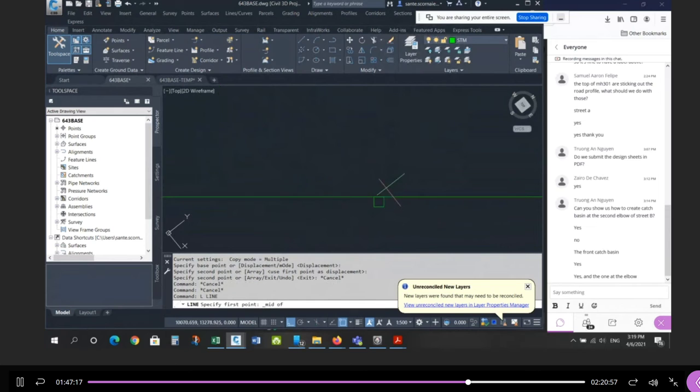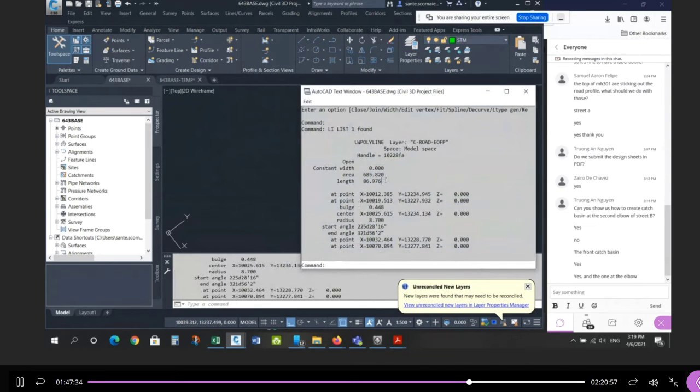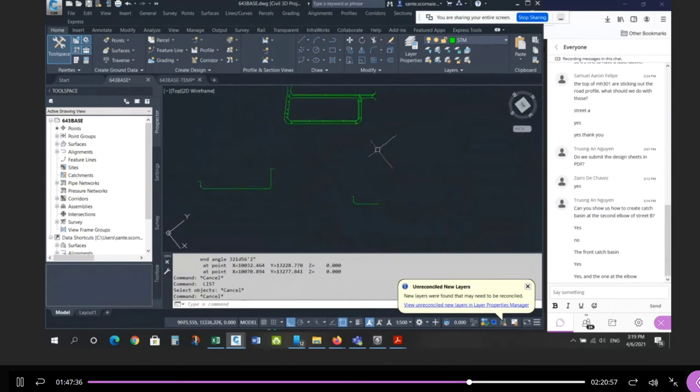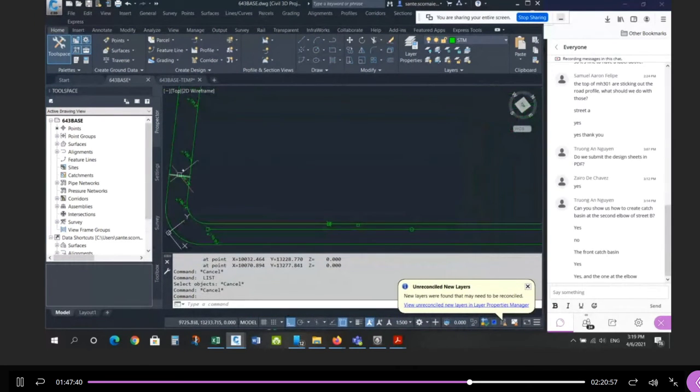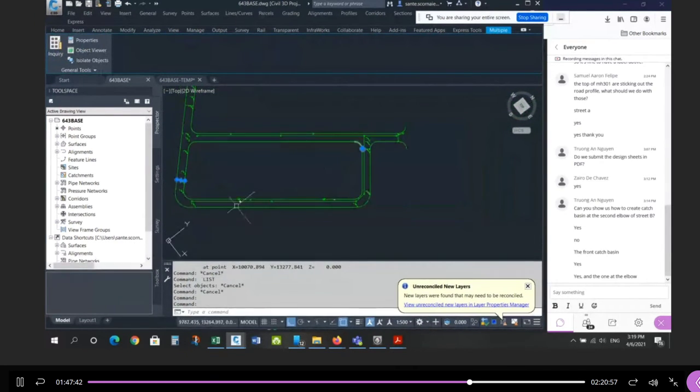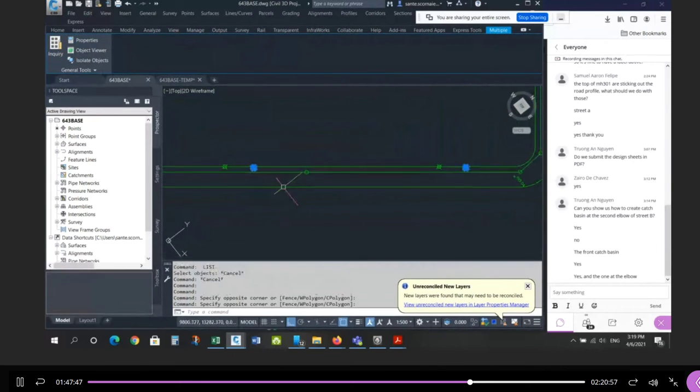All right, I'm going to draw a line from this midpoint, trim it off here. I don't even need the catch basin anymore. And then here, trim it off here. And then polyline edit. Take this, yes, yes, and join all these pieces. This has to be less than 90 meters. 86, good enough, and so on. So I know between this low point and this high point on this outside turn, I need at least two catch basins. And where exactly do they go?